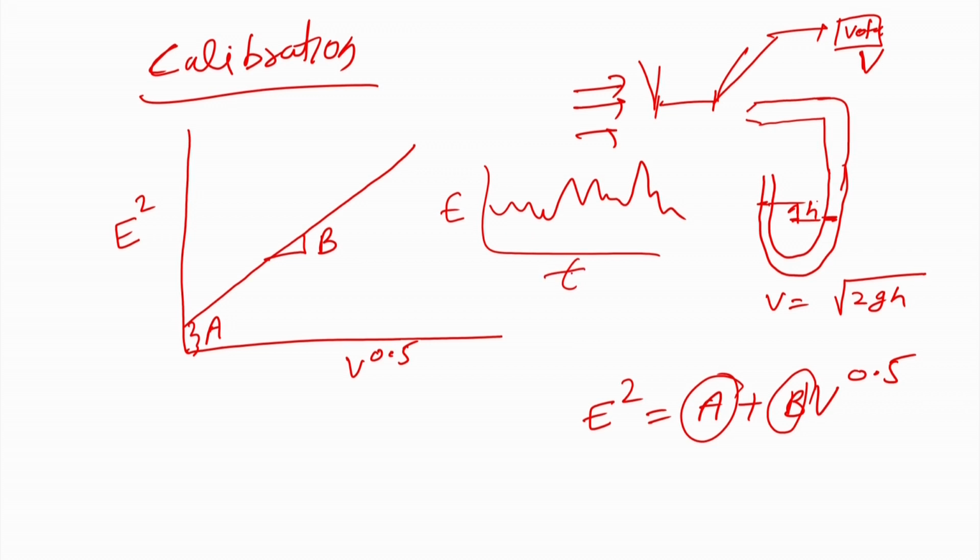This can be calibrated with the velocity, so that you know how the velocity will be. You can calculate the mean with the time average mean value. You can find out what will be the fluctuating component of the velocity in this case. Okay. So, you can do all this with the hot wire anemometer, and that is why this technique is very famous and widely used.